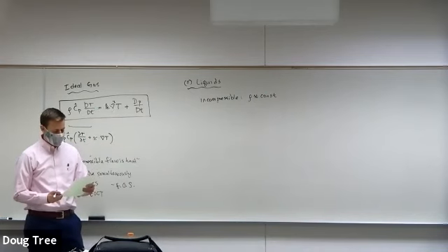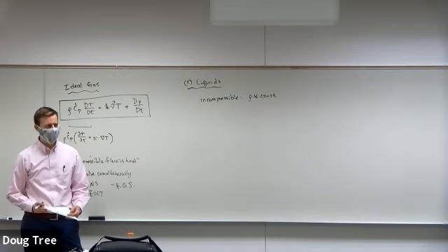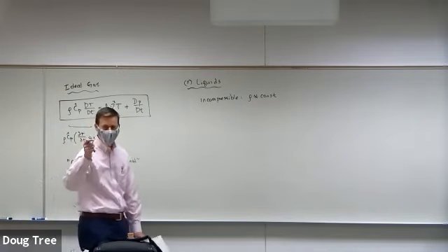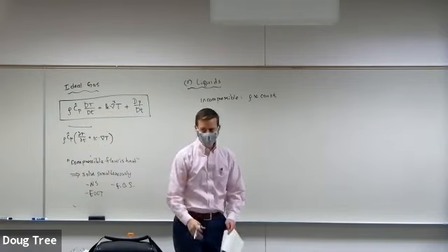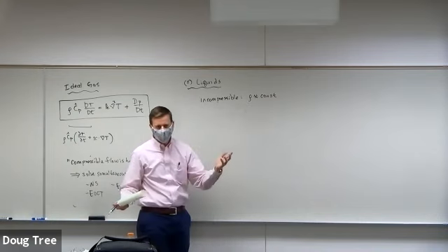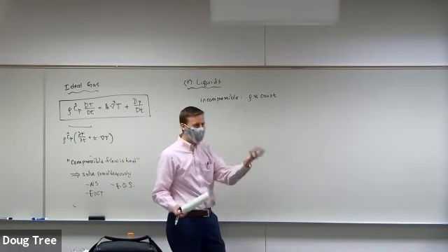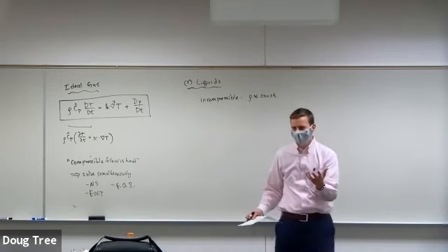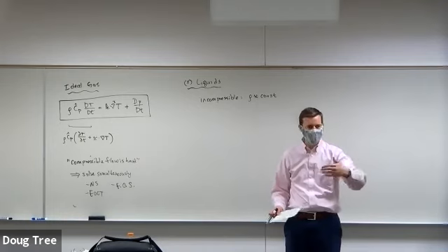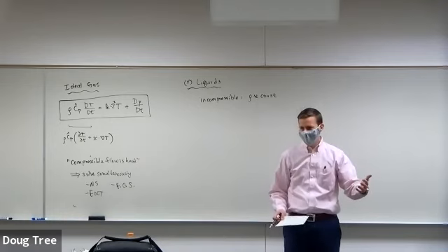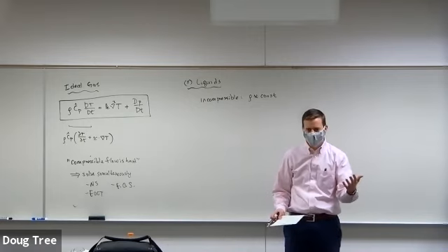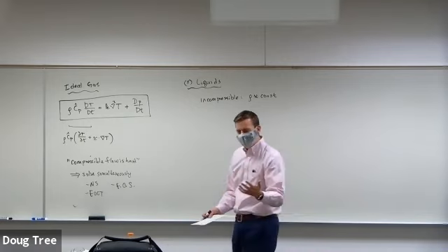Okay, so there's some important consequences of this thermodynamically. So think about that for a second. When I say something's incompressible, now the equation of state is that rho is equal to a constant. It doesn't depend on pressure and temperature anymore. So pressure becomes something weird, right? If I change the pressure infinitely, nothing happens to the density. So it's not the same thermodynamic pressure anymore. It's a mechanical pressure. I think I've said this before in class. But now I've got to think about some stuff.